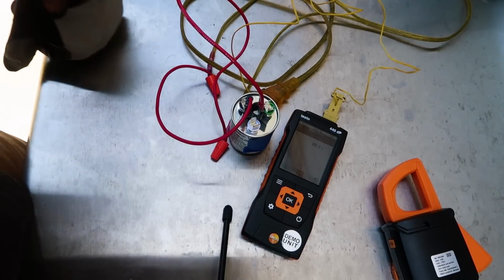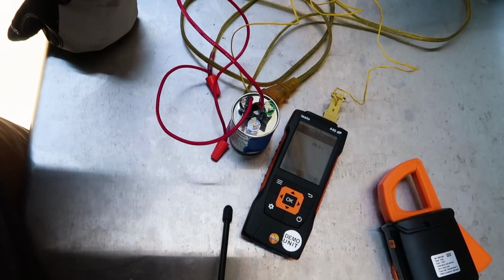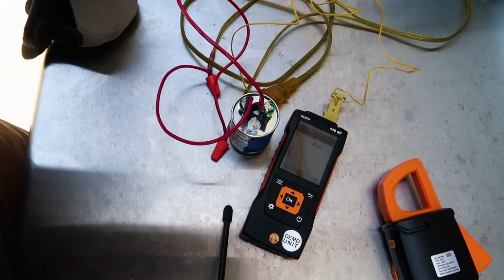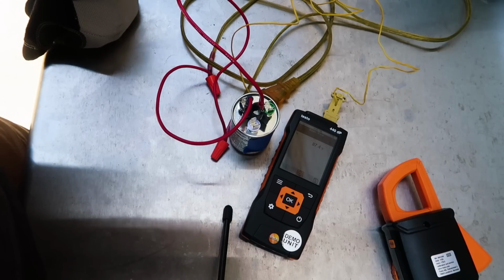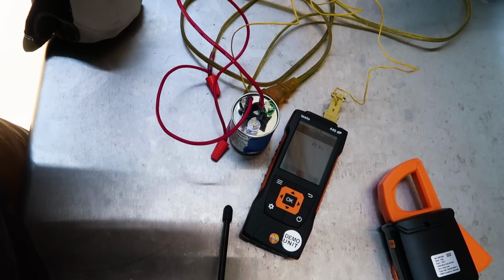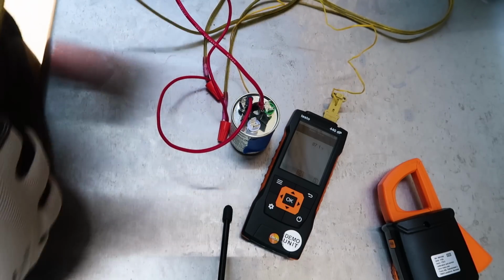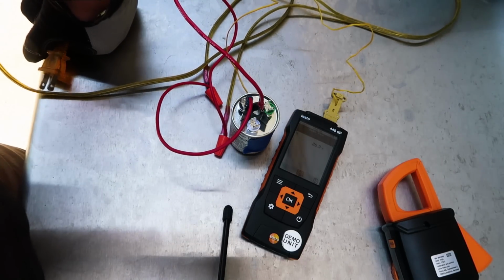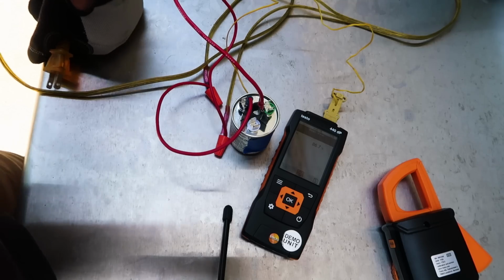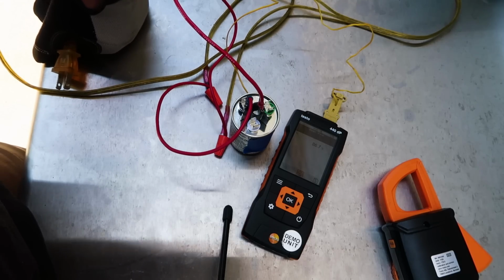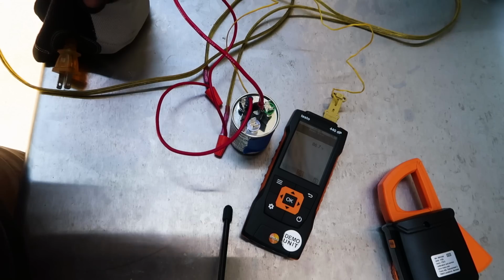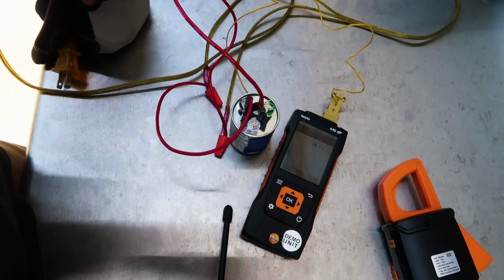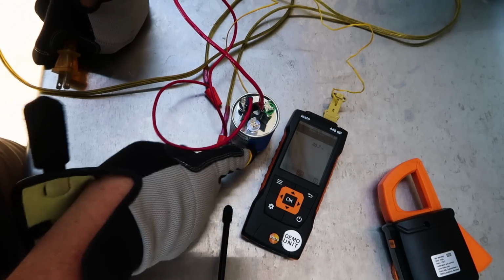Now, one thing to know about these is that they are rated at over 150 degrees Fahrenheit. So regular ambient conditions shouldn't cause these to fail. But what we do know is that increases in ambient conditions can cause them to fail earlier than they would otherwise. So it's not like being in a hot temperature environment is going to make it fail. But if you're in a higher temperature ambient environment, it's not going to last as long.